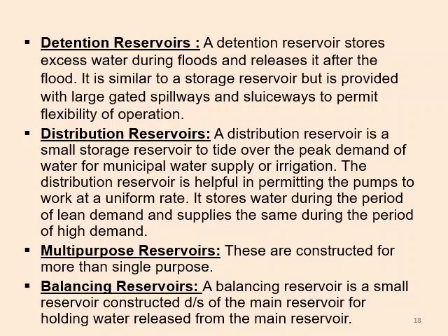Next is the distribution reservoir. It is a small type of storage reservoir to tide over the peak demand for water of any area, maybe for municipal water supply or irrigation purposes. The distribution reservoir is helpful in permitting the pumps to work at a uniform rate. So pumps are also used with distribution reservoirs.